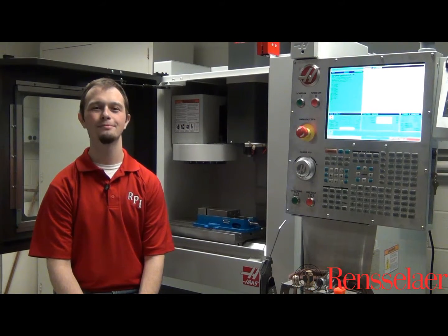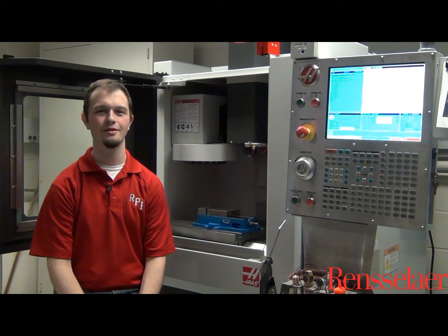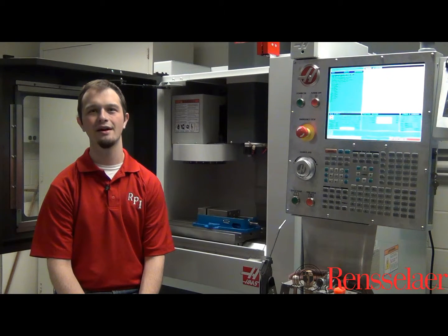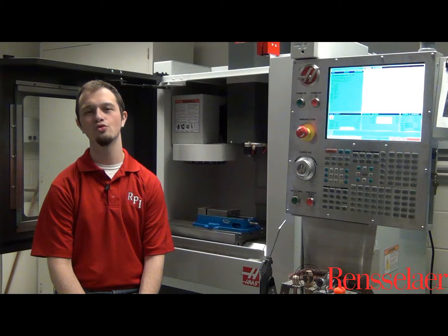As we look deeper into the microstructure properties during a micromachining application, we see that because of the heterogeneous effect, we're going to see greater force variations than what we see at the macro scale. These greater force variations will lead to vibrations and an increase in tool wear, as well as to surface roughness and burr formation differences as we pass through the various grains of the material.